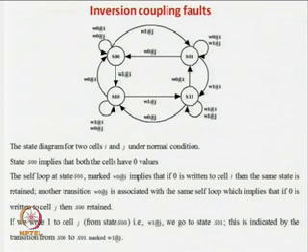Okay, so now let us try to represent this with a diagram. This is normal. Now for that we know that we require I and J. We require 2 cells for representing a coupling fault. For representing stuck-at faults we just required one state, S1 or S0, but in case of coupling faults we require 2 cells to be used. So the idea here is that I have 2 cells, I and J. So there are states 00, 01, 10 and 11, basically S equals I and J. The first bit corresponds to state I, the second bit corresponds to state J. So 00, 01, 10 and 11.